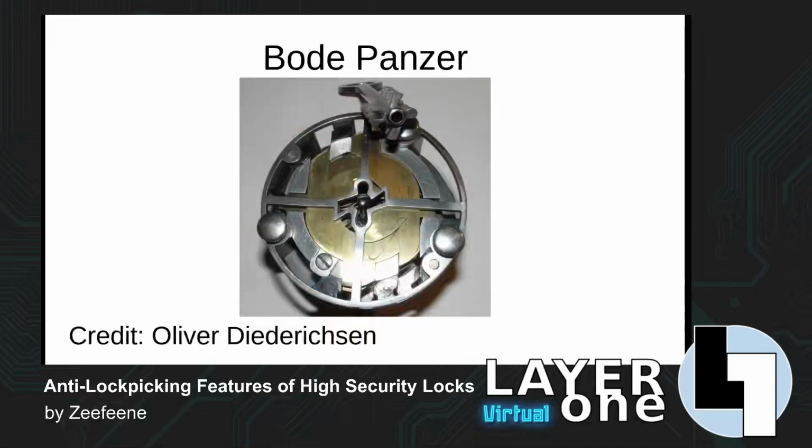there. Of course, if that weren't intimidating enough, this is the Border Panzer design. That is the exact same sort of mechanism, but this time it features wafers that slide left and right and up and down, and the key features 4 beards. So this is phenomenally complex to pick, and unfortunately very rare.